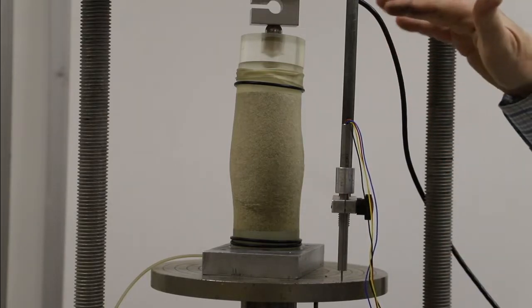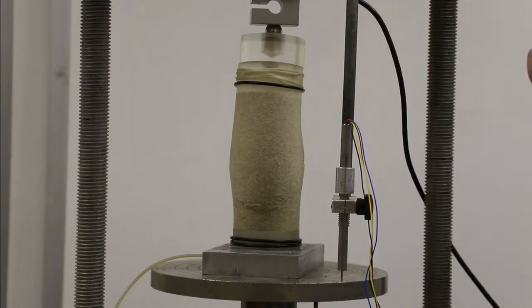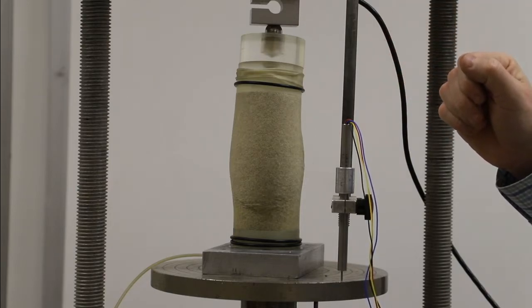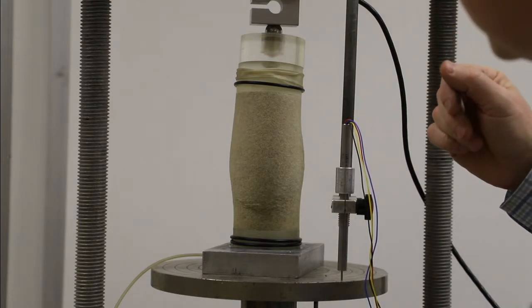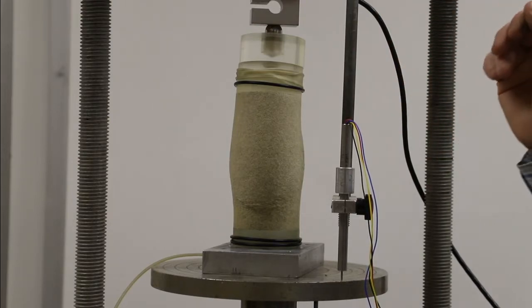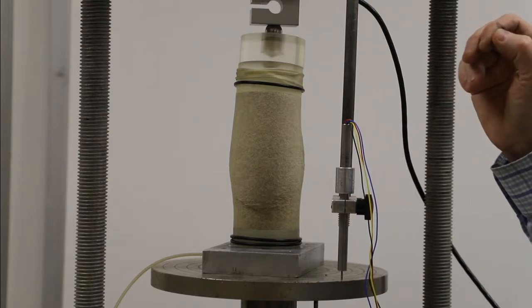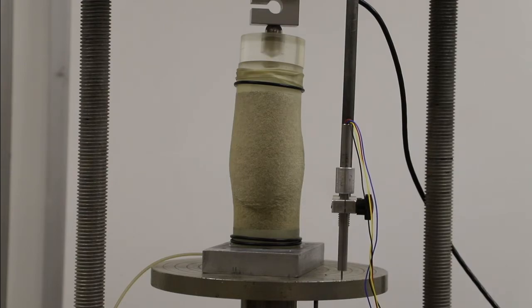Finally, we are getting rotation of the top cap. It's actually tilting, the top cap's tilting away from you. It's probably a little hard to see. But this often happens at very large strains, where some imperfection or misalignment or something is sort of emphasized toward the end of the test. And so beyond a certain point, the geometry isn't really representative or easy to calculate stresses for. But fortunately, this is well beyond the peak stresses or the strength. And so sometimes it'll show up a little strangely in the stress-strain curve at very large strains. But essentially a bulging failure for this loose triaxial specimen.